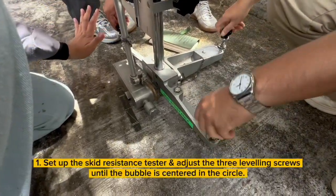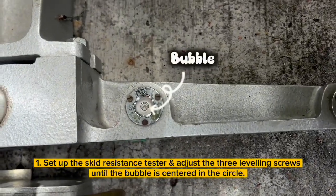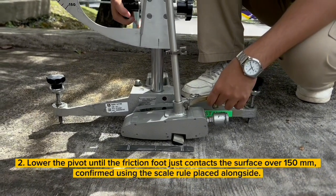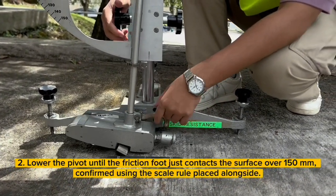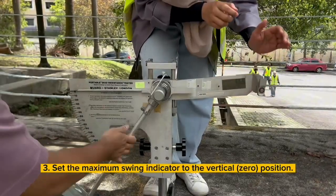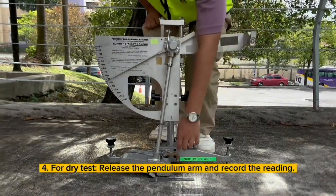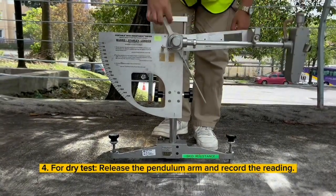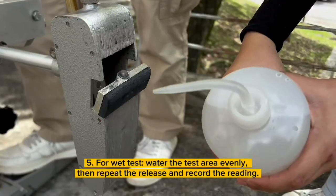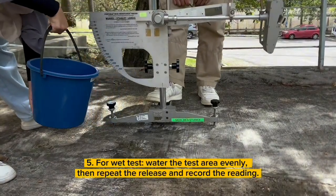Next, for the procedure, firstly, set up the skid resistance tester and adjust the 3 leveling screws until the bubble is centered in the circle. Next, lower the pivot until the friction foot just contacts the surface over 150 mm. Confirm using the skid ruler. Next, set the maximum swing indicator to the vertical 0 position for calibration. For the dry test, release the pendulum arm and record the reading. Next, for the wet test, water the test area evenly, then repeat the release and record the reading.